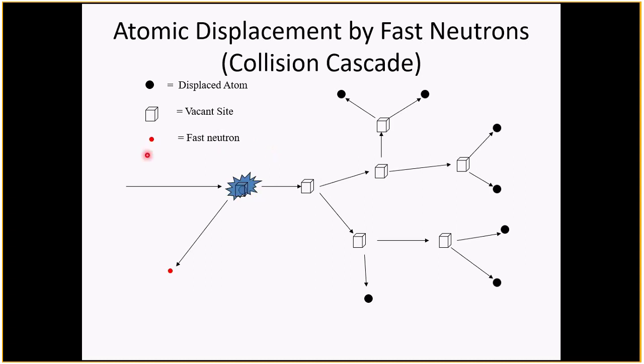Remind you, we've shown you this before, conventional situation where we have radiation damage. How does it normally happen? By far the biggest contributor to displacement damage in nuclear reactors is the elastic displacement. What we have is an elastic collision between a fast neutron, high energy neutron, and an atom, and the energy transferred gives a kickback, a recoil if you like, and that creates multiple displacements and eventually many vacancies and displaced atoms, what's called interstitials, are produced from this one collision event.